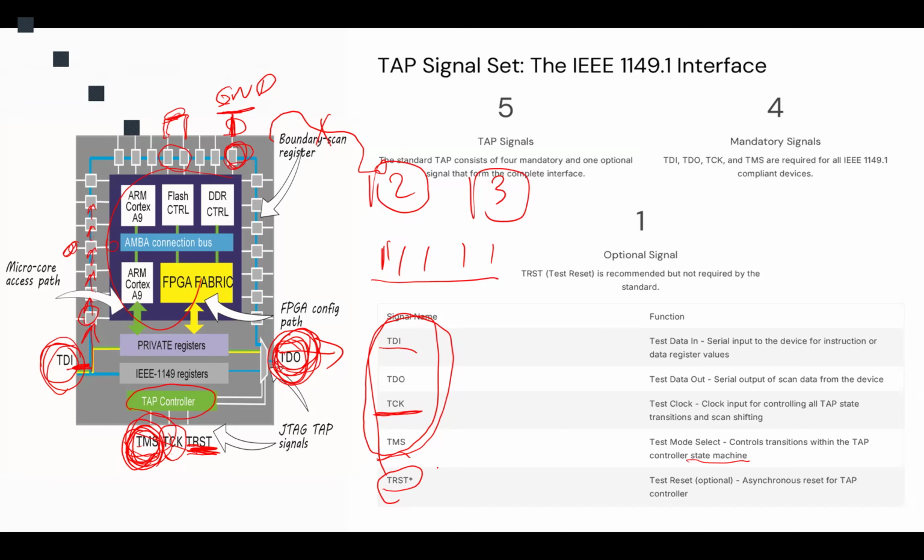So this is basically the whole idea of how we implement the JTAG testing system. What the components are, what the constraints and limitations are, how we have to control that, and what the important notes are, so we can make sure that it doesn't interfere with the core logic, and that the core logic clock and the clock of the tap controller are synchronized with each other, so we don't see any interfered data in our observation points.